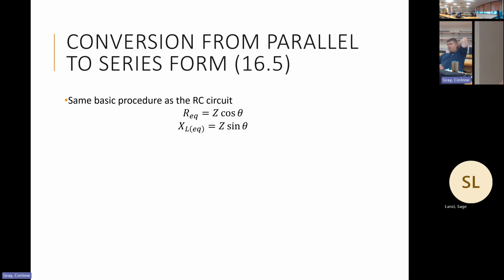So we can convert from series to parallel as well. For this here, we're going through and using the trig information to find the real and imaginary components. So again, this part here for the resistor is real, whereas the portion for the inductor is the imaginary component.